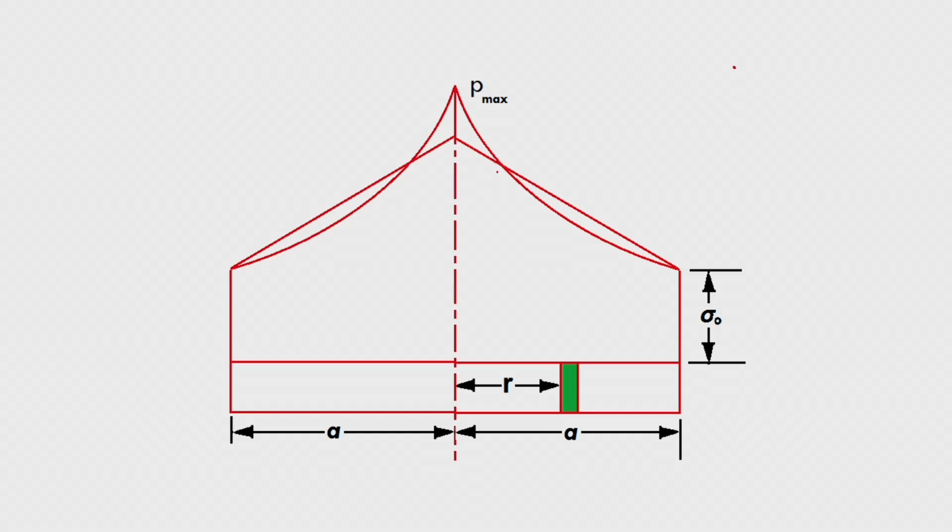From the center up to some distance, you will find that the stress resistance is less here. The moment the stress reaches here, it will start deforming. So, in this condition, sticking friction prevails from the center to some distance. Beyond that, you will find that the lower stress is for the sliding friction.